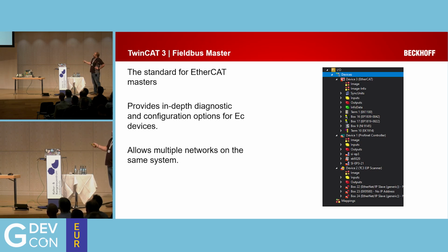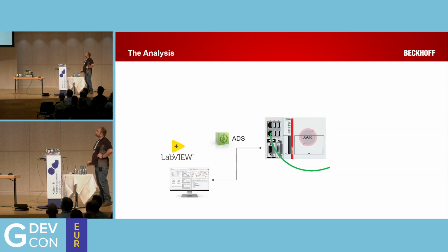We had an EtherCAT master, a Profinet master, and an Ethernet IP network. We had a lot of different devices talking on a lot of different networks, and we needed a controller that could do all of those networks in one go. Yeah? So we took EtherCAT for the Beckhoff hardware, even the NI 9145 that you can see in front of me here. And then we had some drives that were Profinet drives and some Ethernet IP devices that I can't remember what they exactly were off the top of my head anymore. But yes, so TwinCAT was able to run all of that for us.